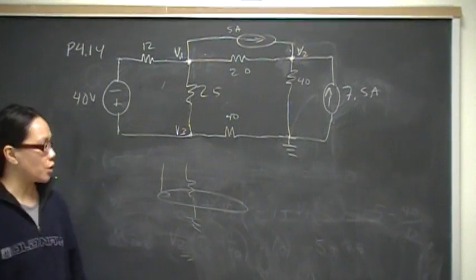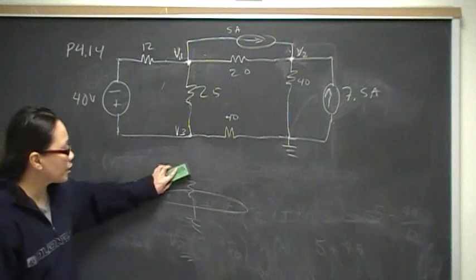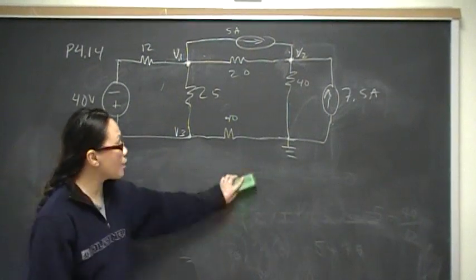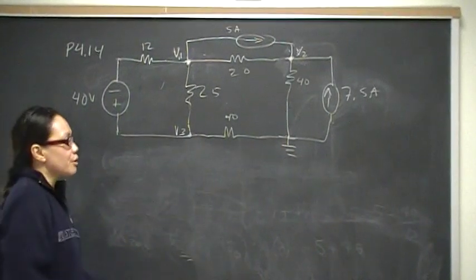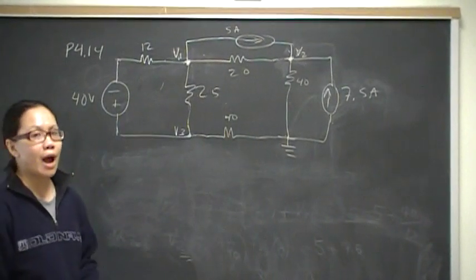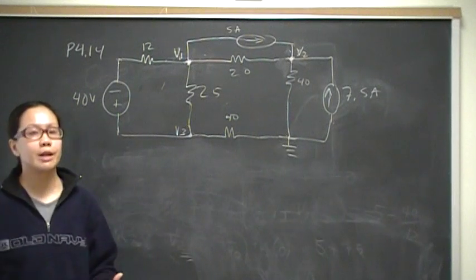It's an essential node, and it's a very natural point of reference to take. So anyways, I picked that to be my ground. That's step number 2. Step number 3, I need to explain what's happening at each of the nodes for our calculations. We're going to start calculating branch currents.